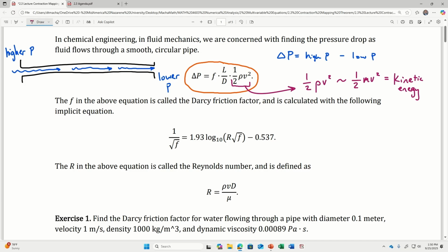There's less resistance. Have you ever, maybe you do this every day, at lunch, drink your lemonade through one of those crazy straws that goes woo, woo, woo? It takes slightly more effort to drink lemonade through a crazy straw than at McDonald's, where they give you a disposable straw with an extra wide diameter because they want you to drink your soda faster, I guess. It doesn't take as much effort with a McDonald's straw. So that's the effect of the diameter, the capital D. The larger the diameter, the lower the pressure drop because there's less resistance.